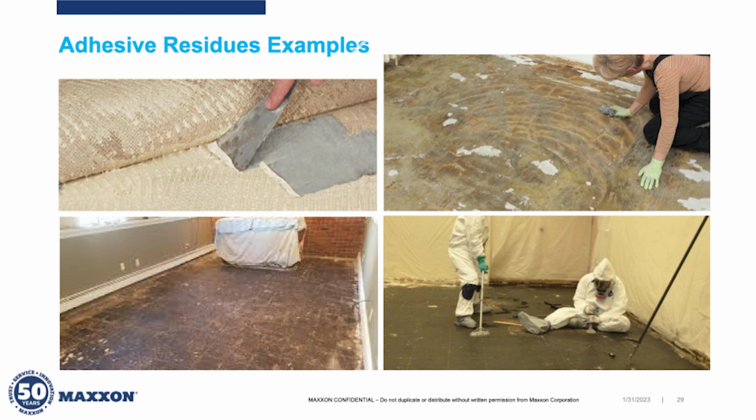And that's a process, and as we said earlier, you're leaving a contaminant behind in this situation, which also has to be dealt with. And then these bottom two shots are showing most likely old cutback adhesive that's got some asbestos to it. And on the right-hand lower corner, you see these two gentlemen who are suited up to do a chemical abatement or wet scraping at the very least.